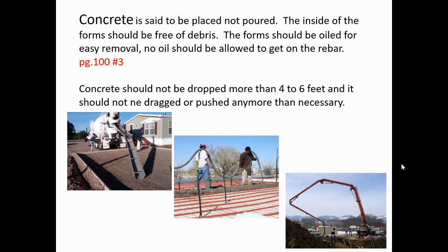So how do you get the concrete in the right place? We talk about how much it weighs. It's a huge amount of weight, right? So you don't want to be moving concrete by hand. The top left picture shows the concrete truck with a big chute, so they can control that chute and place the concrete where you want it. You could get a concrete pumper, where you put the concrete in a pumper and it's got a hose coming out of it, and you can really place the concrete exactly where you want it. But if you look at these two guys holding up that hose, that hose weighs hundreds of pounds because it's full of concrete.